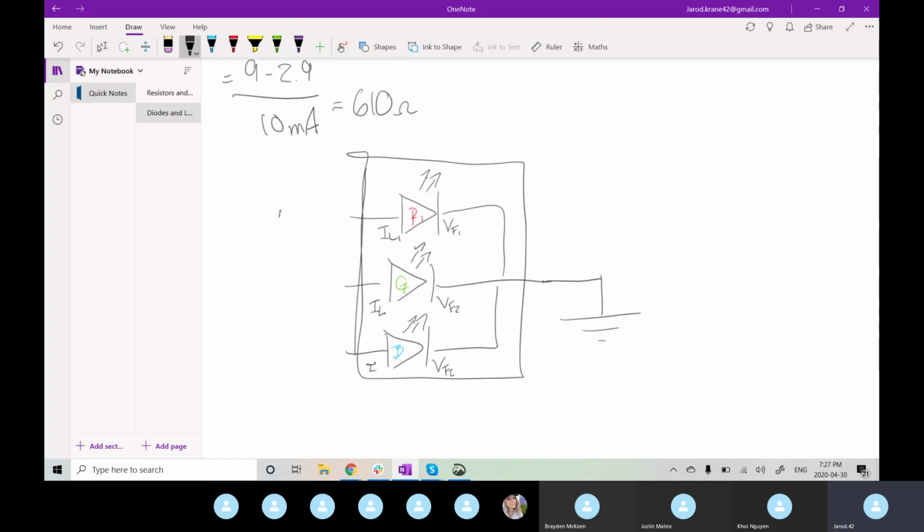I think they're generally spec'd in such a way that it's consistent, but you would apply a resistance to each their own pin, and then maybe that would all tie up to one. So it's essentially like having 3 LEDs in parallel. So they won't directly impact the other based on whatever their voltage drop is.